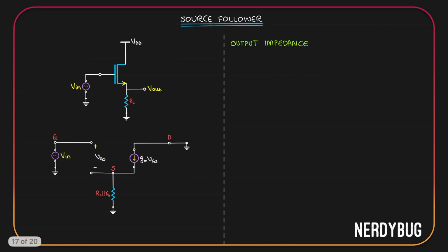Let us now find the output impedance. For that, again, we have to shut down Vin. That makes the gate grounded. What we need is the output impedance, so I'll have to apply a potential Vx at the output and find its relation with Ix. Let us apply Kirchhoff's voltage law. We have the ground here.